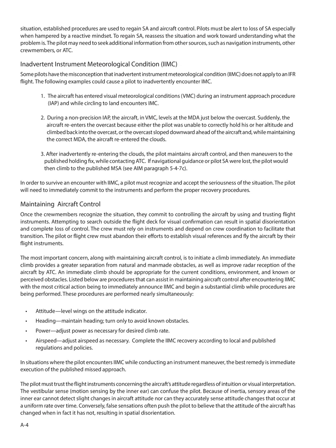Attempting to search outside the flight deck for visual confirmation can result in spatial disorientation and complete loss of control. The crew must rely on instruments and depend on crew coordination to facilitate that transition. The pilot or flight crew must abandon their efforts to establish visual references and fly the aircraft by their flight instruments. The most important concern, along with maintaining aircraft control, is to initiate a climb immediately.